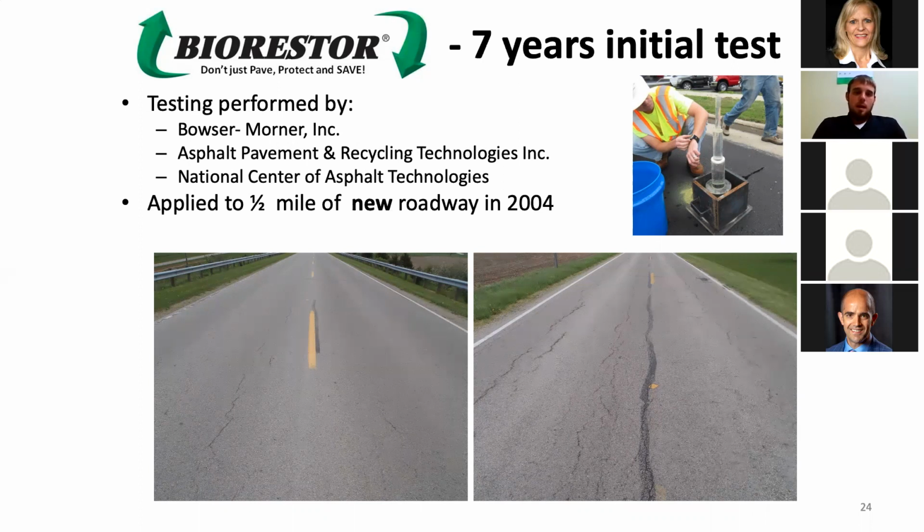There was testing done by Bowers and Warner, APART, or Asphalt Pavement and Recycling Technologies. We've had testing throughout with the National Center for Asphalt Technology, but the main thing in this picture is the amount of deterioration that has not occurred in the treated section. This county engineer stated that it's hard to say on a general basis, but for this particular road, he received a 40% additional life cycle for a 13% additional cost of the treatment.